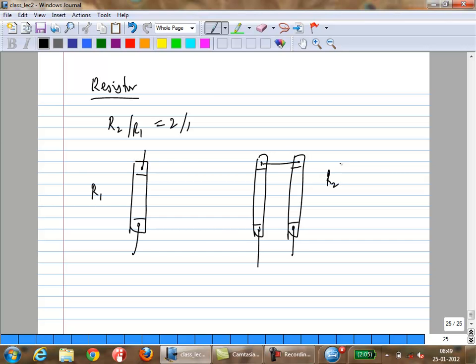So the actual resistivity could change in one direction, right? You could have a pressure change, right? When you're creating your mask set, you could have a gradient on that in the lithography. So there are lots of systematic errors you can introduce while creating these resistors. Or it could be transistors, right? In the case of the transistor, these deposition rates could lead to a change in VT, it could lead to a change in doping concentration, mobility, right? Lots of things. And there are certain set ways to deal with these kinds of effects.